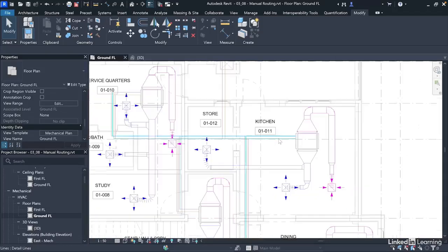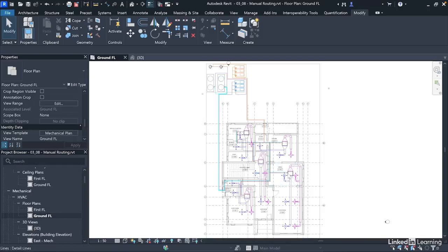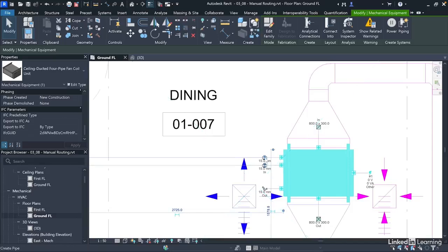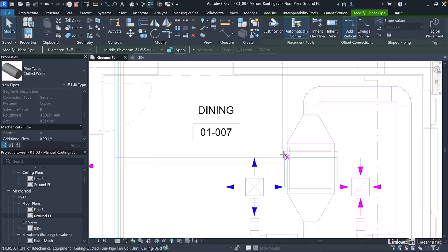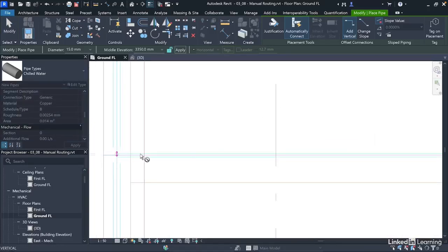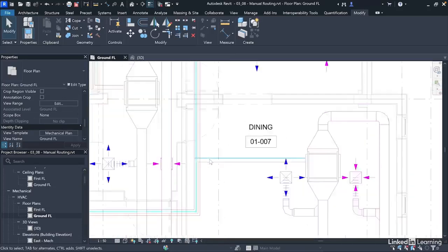So you see that. Second way is I can actually draw it out from the component the same way we did for the chiller here. So I can come to this fan coil unit and I click on this icon. Because you have two connectors above each other at that point, you still need to specify which of them. So I'll still pick chilled water from here, and then I draw this, then go and touch this particular pipe here. If it does not touch, because I have a line there, I can just use the trim command to join it, trim extend command, and you need to make sure that you see this fitting at that point.